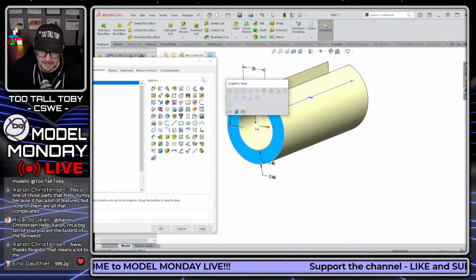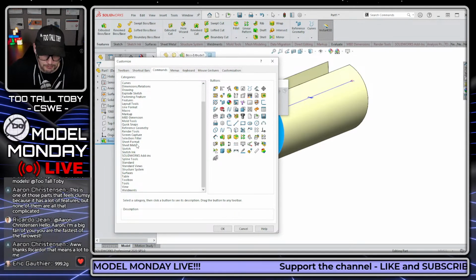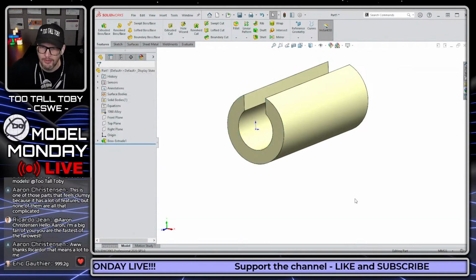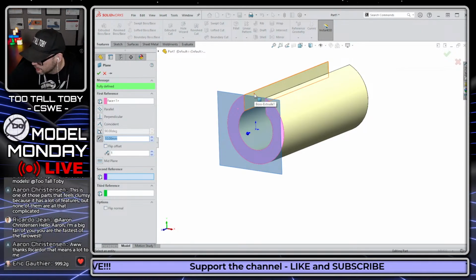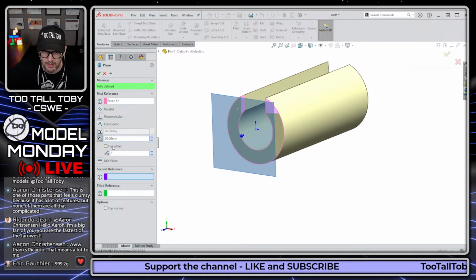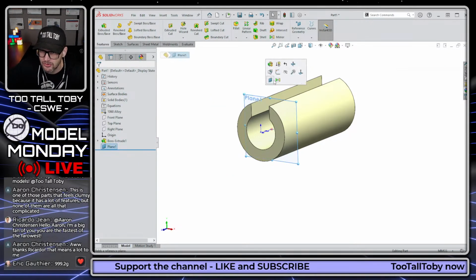Because what that means you can now do, and you would get that from, I think, is there a reference geometry section? Yeah, reference geometry, planes, boom, add that on there. And so what that allows you to do is anytime you select a face, you can just jump right into planes, boom. So this is going to be a new plane offset at a distance of 20 millimeters. And then I'll just flip that offset and hit the green check mark. And now I'm ready to create my second feature, which is going to be that angled leg.